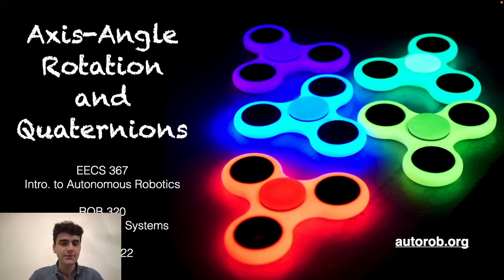So the topic for today is going to be how we can represent what are called axis angle rotations for our rotational joints within robots. So we'll talk about a number of different ways that we can represent these transformations, including what are called quaternions. So this material will be useful for the upcoming assignment 4.